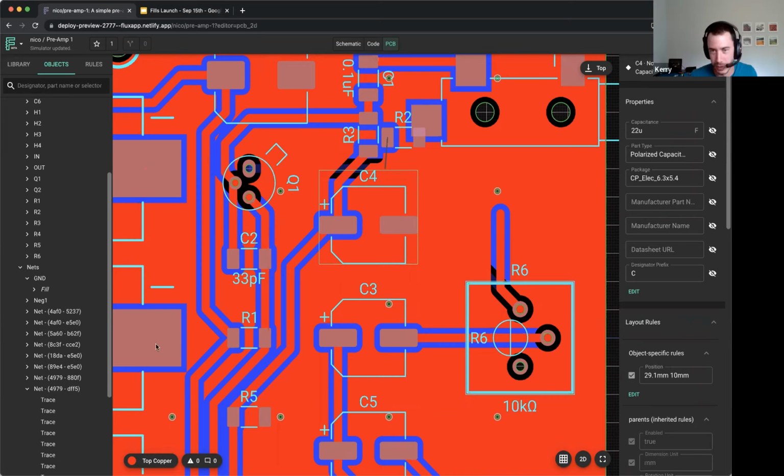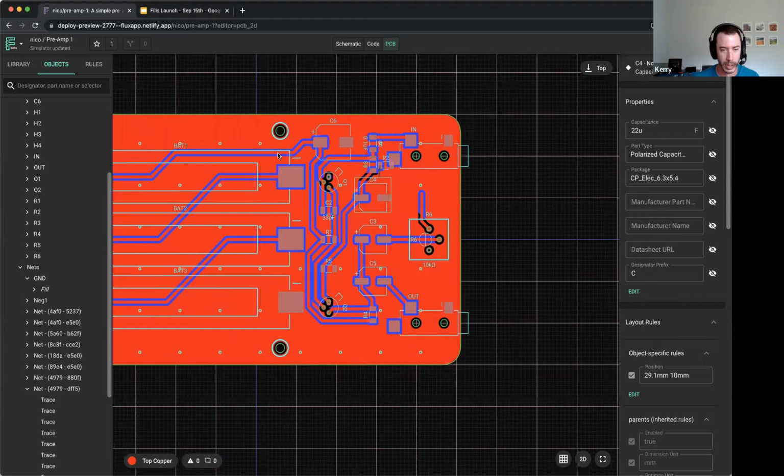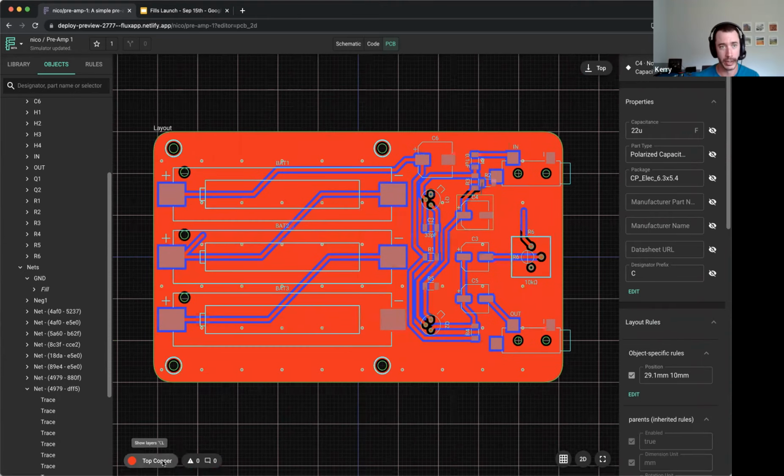Yeah, hatched ground fills, man. Hatched ground fills are important in a couple of different circumstances. I won't take up too much of your time because I had a session last week where I talked about it for almost 30 minutes straight, which was fun, but I don't know how fun it was for the people listening. So instead of doing a completely solid ground fill like this is, you could do different hatch patterns. Usually how I've seen it is you define the percentage of copper that you want, or the percentage of void. And so you do something like, I have 60% copper coverage, I have 70% copper coverage.